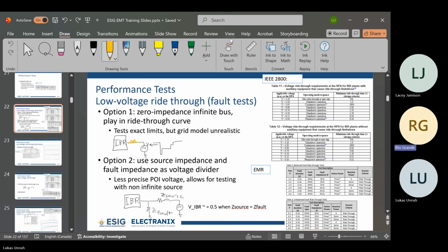The large load event looked like a lot of it was 5 reclosings in a row. They probably don't have the same controls like this. For some reason, for their power quality requirements, that many reclosings in that short of time, they tripped offline. Probably not the same function or the counter or whatever, but there was something with that amount of rapid closing or dips that caused them to trip offline.